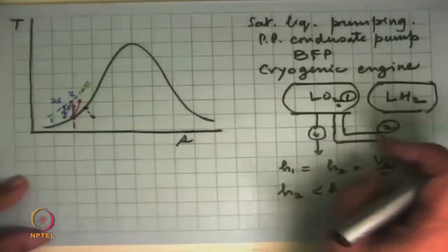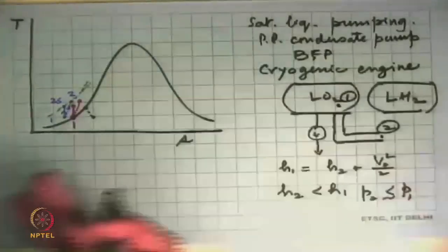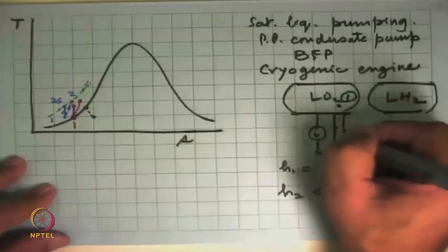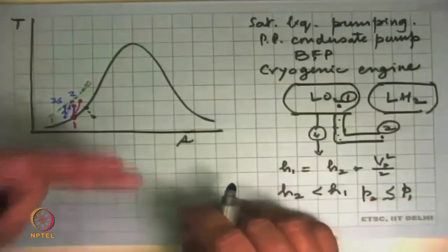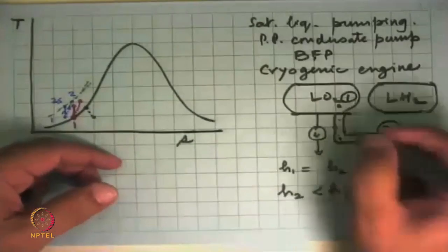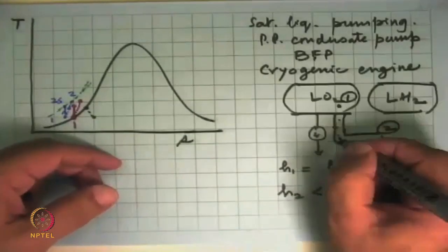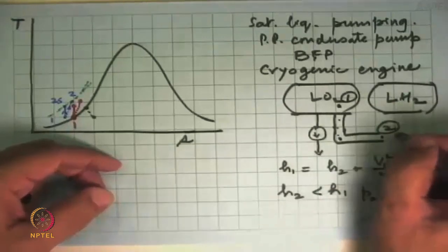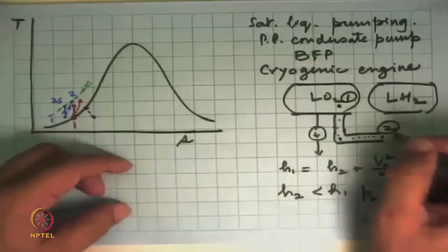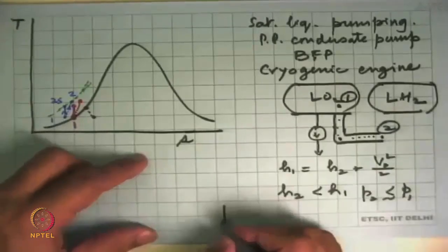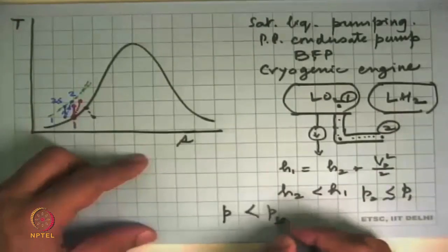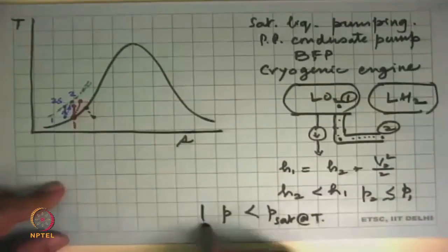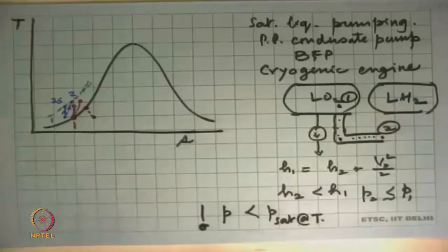And so we have to ensure that we give at least minimum some static head, so that this is saturated liquid, but as it goes down, the gravity head rho GH adds on to it, so the pressure here under no flow will be more than the pressure here, so it will be slightly subcooled liquid, slightly compressed liquid. Then as you pump it to the pipe up to the inlet of the pump, the pressure drop will take place, but at no place do we ensure that pressure is less than P sat at the given temperature. This is a very important consideration in designing all these type of devices.